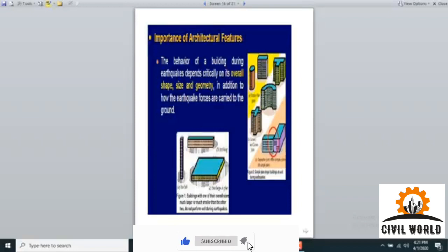In this figure we are shown 4 or 5 types of structures based on various geometrical figures. You can see this is called a cylindrical structure. You can see it is elliptical in the surface area. So this is considered to be ideal as far as an earthquake is concerned, or even wind force. Cylindrical structure is most ideal. Same is a square structure of a small, or moderate, surface area. You can see this is a structure which is very well proportioned along the x-axis, along the y-axis, and also along the z-axis. So this is a suitable one.